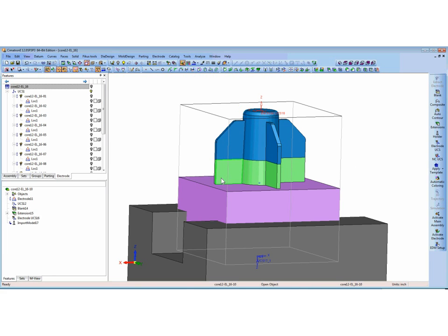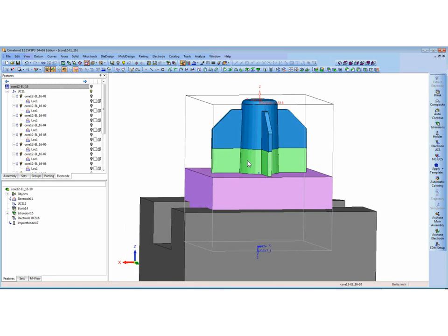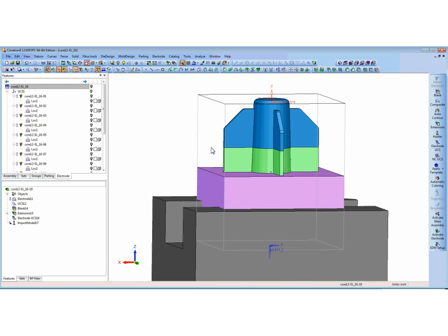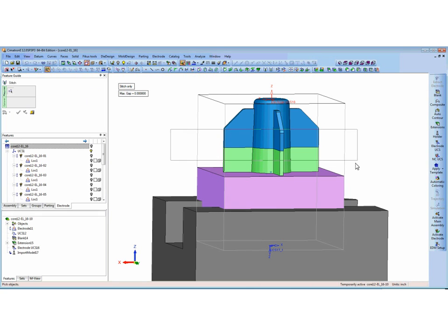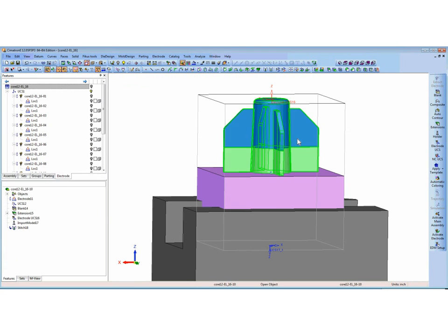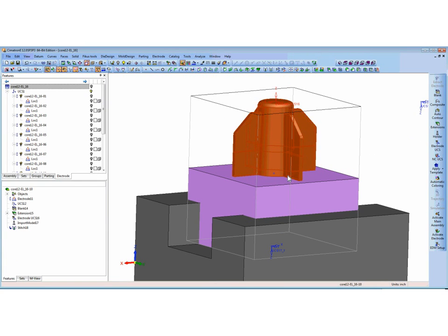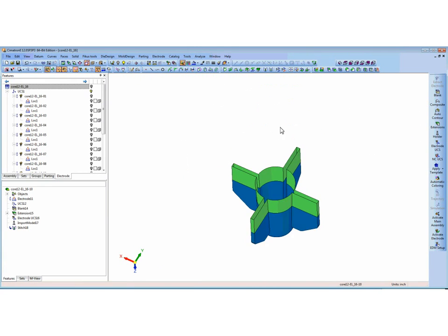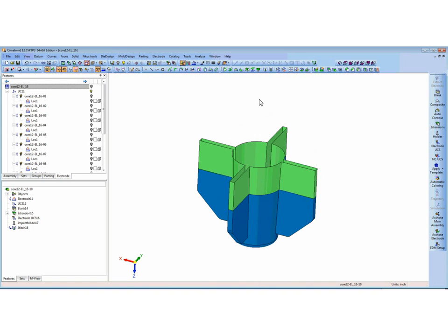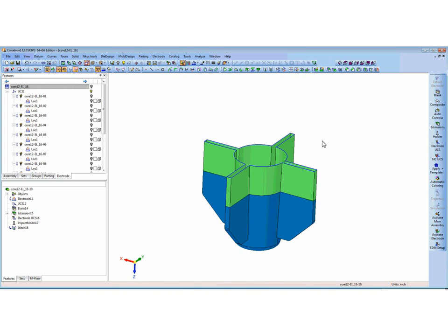And when I put the extensions on it, each one of these is an individual surface, but they're also individual bodies, which is a little bit hard to think of sometimes, but I can stitch these together. Okay, and now this is one body, but it's still open. And I want to hide everything else and show you that if I were to show the open edges on this, you'll see that this whole bottom here is all open.